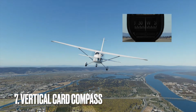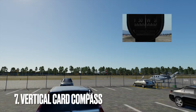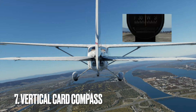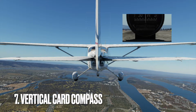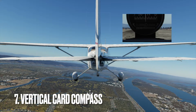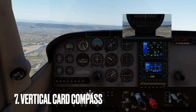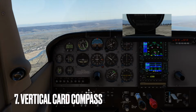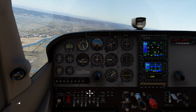For example, during visual navigation, the vertical card compass helps the pilot maintain the desired heading when flying in areas with limited or no navigation aids. Magnetic heading information is essential for accurate navigation, especially when flying in areas with magnetic variation. An interesting fact about the vertical card compass is that it uses a magnetized card and a damping system to provide stable heading information despite aircraft maneuvers.